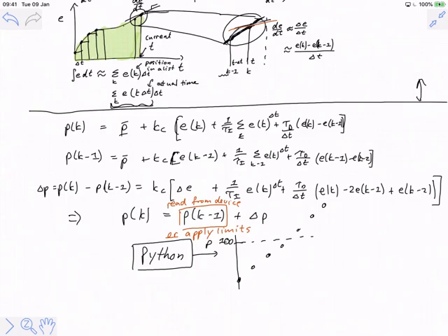And so I recommend that when you are testing your code, you test in a couple of different layers. I recommend that you test your controller code first using a completely smooth transfer function, like your first order model that you fit onto your TC lab, without even using the TC lab model, which contains noise. That way you can verify very easily that if you make small set point changes, small enough so that you don't saturate the heater output, start at 50 and make a 1 degree Celsius set point change. Remember, on your linear model with your linear controller, that will give you exactly the same behavior as if you made a 10 degree Celsius change.